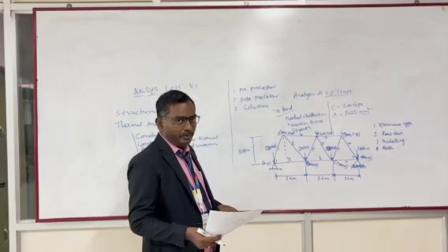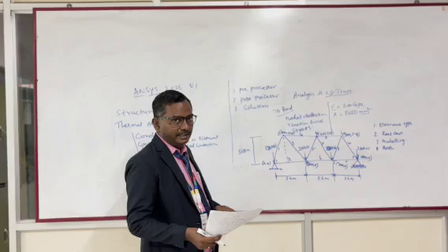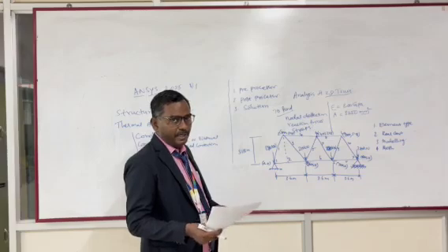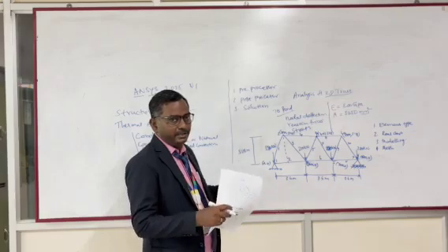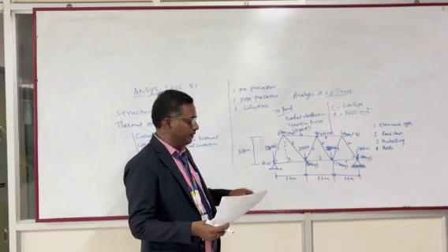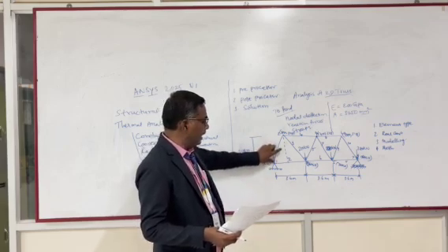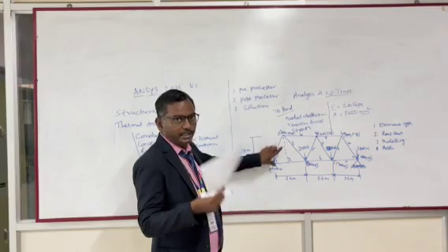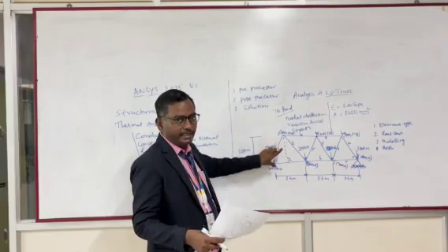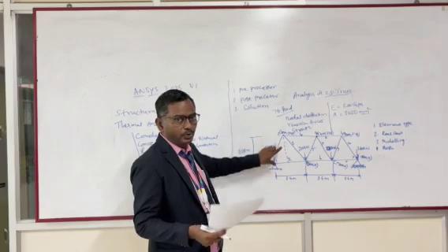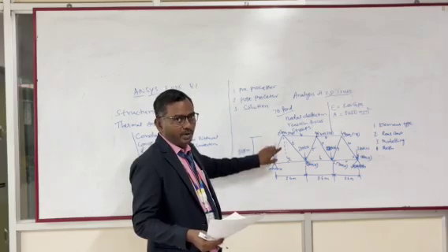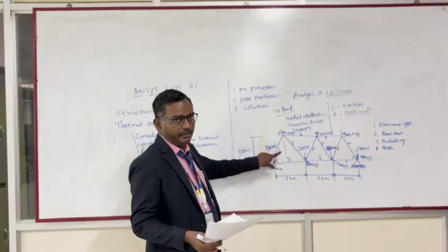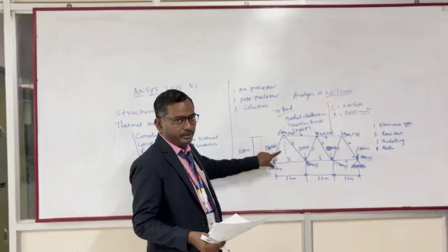Beam problems, you can select that 50 or 100 whatever divisions you can select. You can select that key point distance 1 to 2. You can divide into 100 or 1,000, whatever you want. You can divide the divisions.